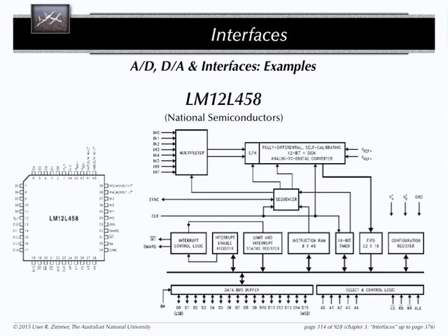That means this is the one wire which always has to be triggered when any communication with this one happens. And this is also the wire which you use to place your chip into a certain memory area. So one thing which is not on this picture here is an address decoder. You want to have this appearing in a certain area of your memory, which means that whenever a certain combination of addresses appears on the bus, this address decoder says, that's mine.